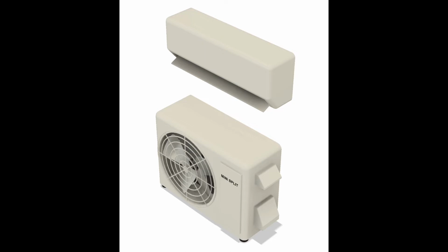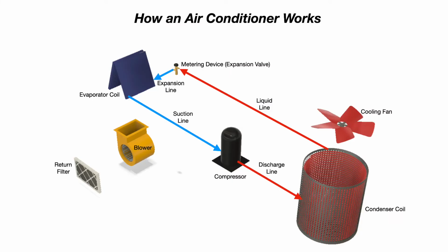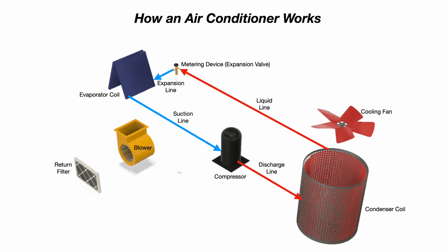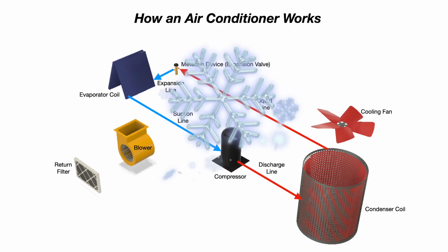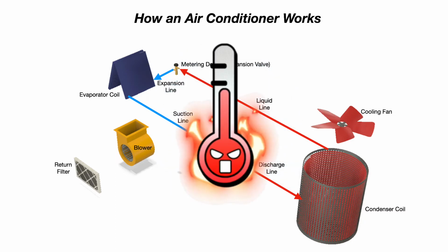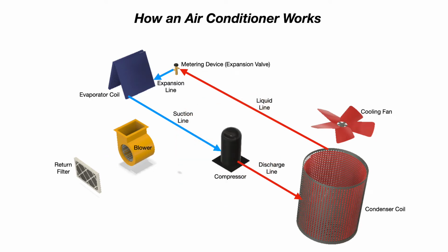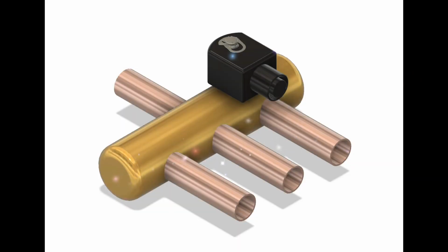Same thing with a standard split system like you see here in this picture. Some just do air conditioning. But if you specifically buy a heat pump, the key difference between a standard split system and a split system that is a heat pump is that the heat pump system will provide cooling in the summertime, but it will also provide heating in the wintertime. The key component in a heat pump system that accomplishes this task is a four-way reversing valve.